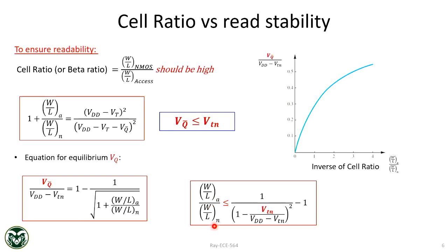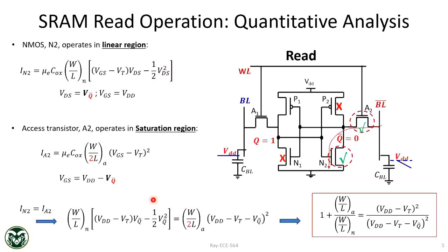Because if you look at this picture here, if this transistor is weak, this transistor will dominate and Q will be always close to 0. But if you make the access transistor weak, it means low current. What parameter in the memory operation will suffer? Huh? Time and also write. Both of you are correct. So one is read time will be very, very large, right?